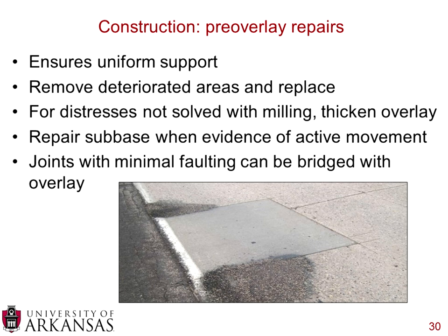You can see here a picture of, it looks like there is either a little bit of corner cracking or some sort of deterioration of the corners there. They just simply cut that out and replaced it. And if you have any sort of distresses that were not solved with milling, you can simply thicken the overlay.